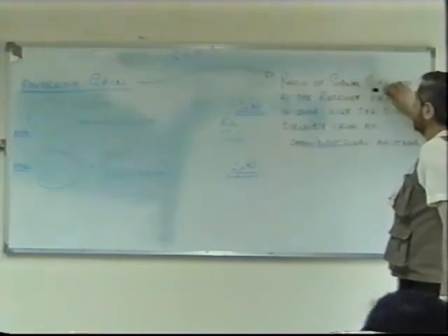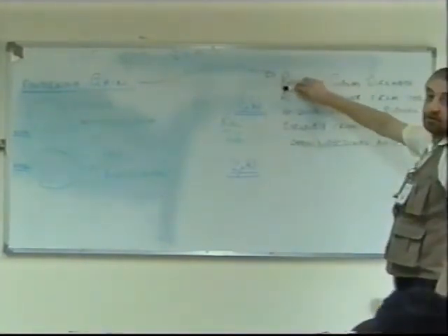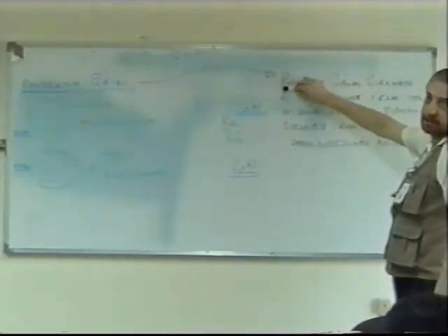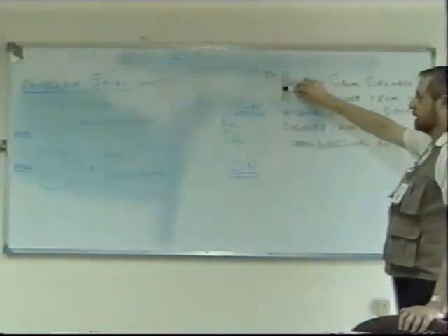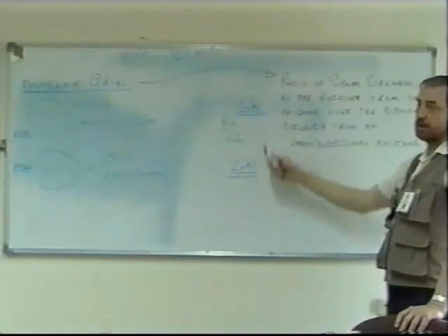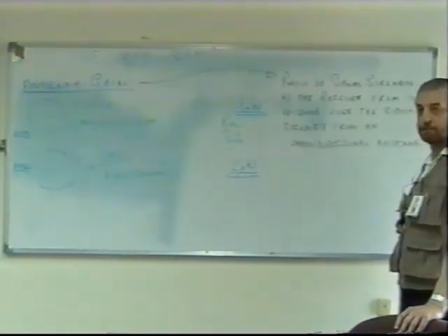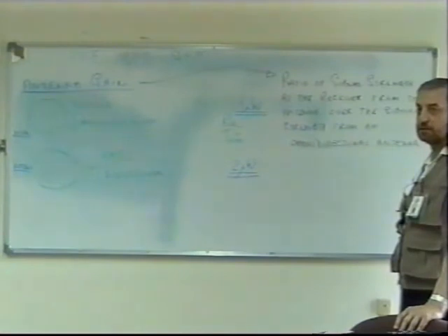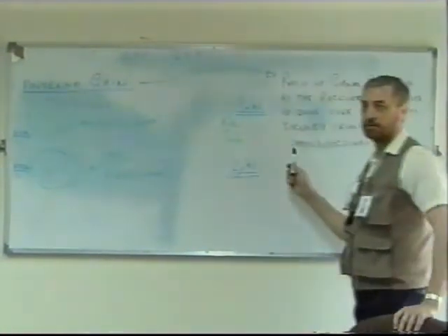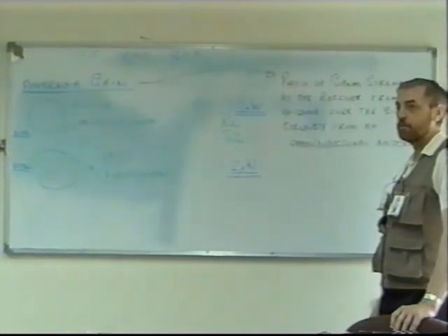This is where we talk about ratio, and whenever we talk about ratio, we can express it in decibels. 10 log times the ratio, and that will give me 3 decibels if it's twice the power, 3 dB. 500 watt from antenna or from TX? No, that's the power of the transmitter in that example. Say this is the transmitter, this is the receiver. From antenna, how much?